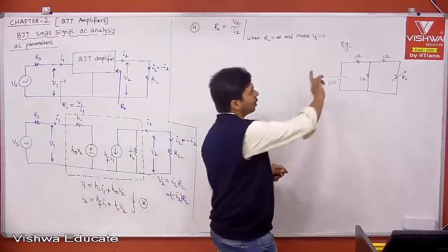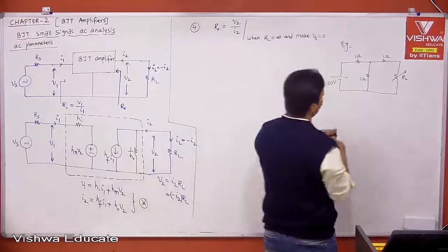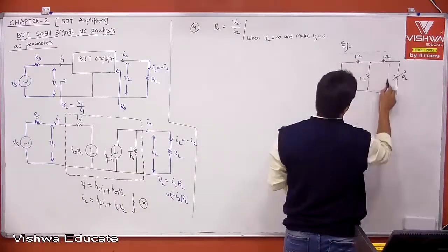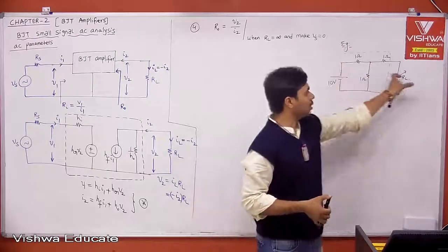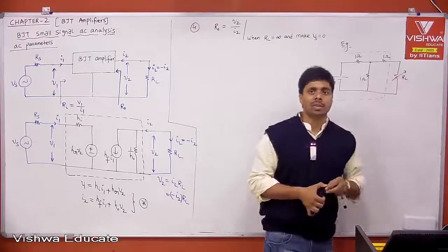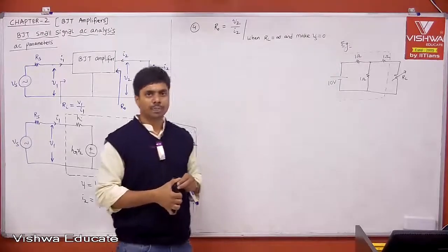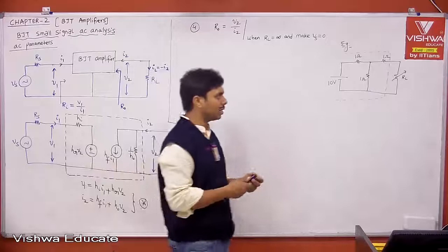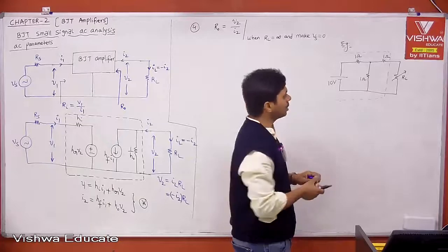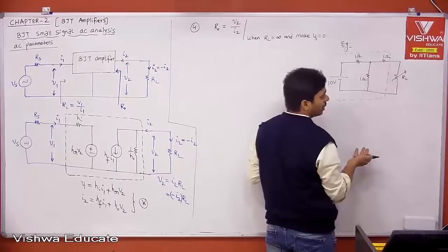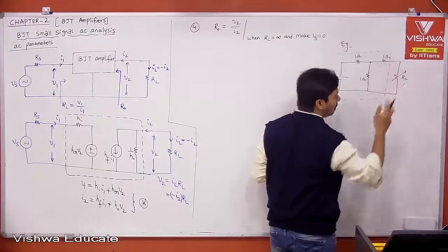Applying nodal analysis every time is difficult, so we can use Thevenin's theorem, which is easy. Once you replace the complete fixed circuit with some VThevenin and RThevenin, then whatever the load value, it is easy to calculate the voltage using the voltage divider, and the current flowing through the load. Now tell me, how will you calculate VThevenin? We need to exclude the load; whatever voltage you have at the open terminal is VThevenin.